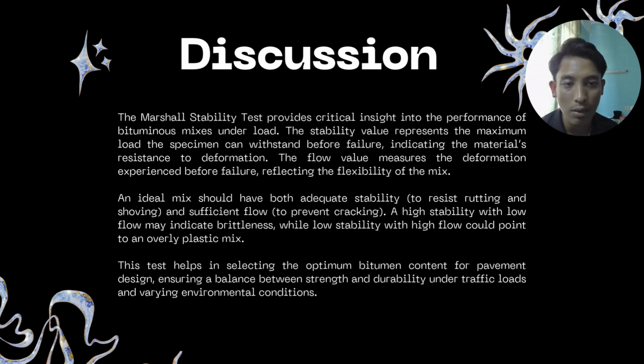A high stability with low flow may indicate brittleness, while low stability with high flow could point to an overly plastic mix. This test helps in selecting the optimum bitumen content for pavement design, ensuring a balance between strength and durability under traffic load and varying environmental conditions.